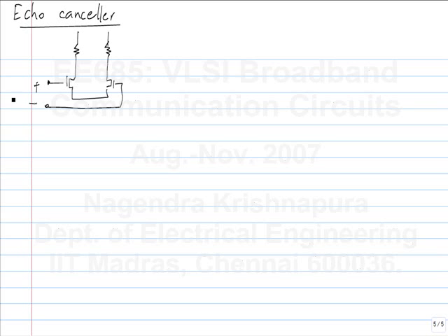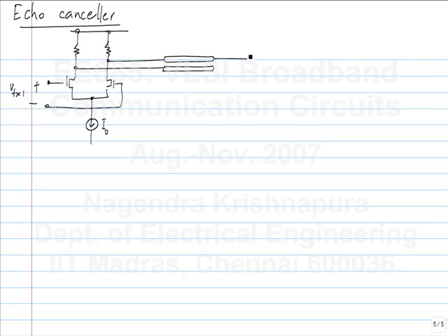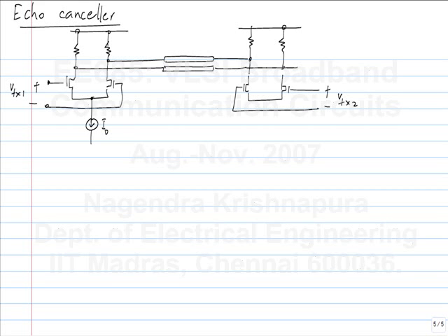Okay. So let's say this is the first transmitter and it's trying to switch a current I0, and of course other things are connected to it. Each of these is a 100 ohm transmission line, but anyway that is irrelevant because it is terminated perfectly. So it is connected up like this, and this is the transmitter part. You have a transmitter connected at either end of the transmission line, and then to receive the signal coming from this side, you have a receiver.